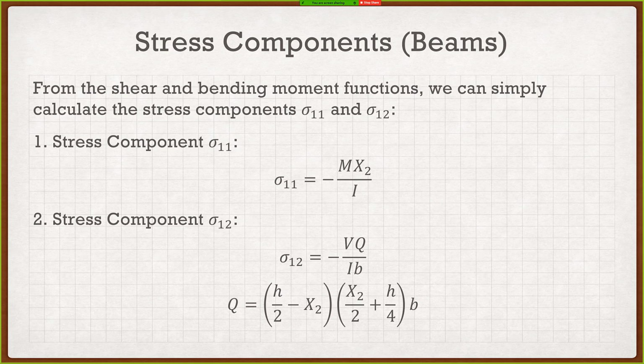So if we take a step back and we look at this, our two stress components have two nice equations for them. All I need to do to solve for these two components is find my moment function and find my shear function. How do I do that? Well, they're simply calculated from that deflection function. So that's not going to be a problem at all. Again, this is just a straight repeat of assignment number 7. So if you guys have Mathematica code, you will actually already have these functions ready to go.